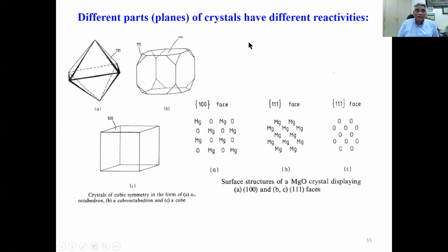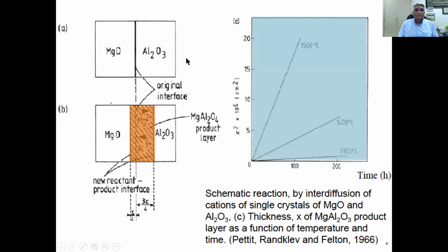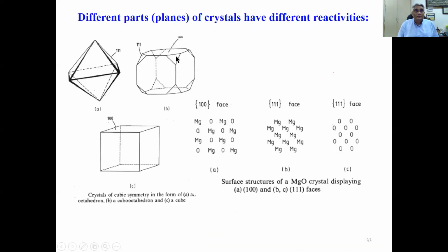By causing the diffusion to happen, if the 100 phase of one of the systems is intact, and if the 100 phase is also existent in the final compound, that becomes a platform for magnesium aluminum oxide to form, because that 100 phase is already present in one of the constituents. So nice to see that, right? All the 100 phases become the platforms for nucleation, and the new phase starts building up there, and finally the crystallization process will complete.